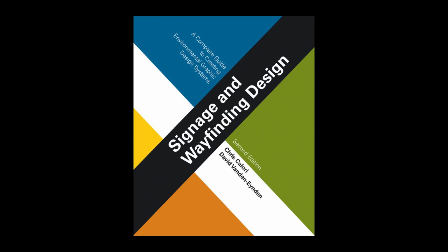The sign numbering system, sometimes called the location numbering system, identifies and distinguishes each sign unit on the location plans and the message schedule. The sign numbering system is itself a coding system that conveys distinguishing information about each sign unit. To effectively track all the signs in a program, each sign should be assigned a unique sign location number, meaning it's not duplicated somewhere in the program.